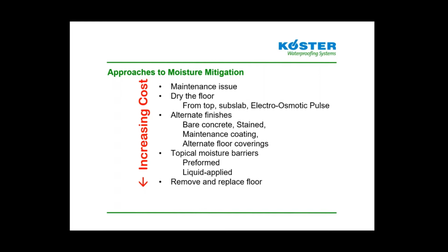the entire floor. When possible, it's desirable to dry the floor, practically speaking, obviously from the top of the floor. Dry and warm circulating air can help, but air warmer than 80 or 90 degrees can have a negative impact on some of the other building finishes if there is casework, cabinetry, for example, in these areas. That very high humidity and very hot air can have an effect on any of the other finishes in the space. That's something to be cautious of if an attempt is made to dry the floor out.